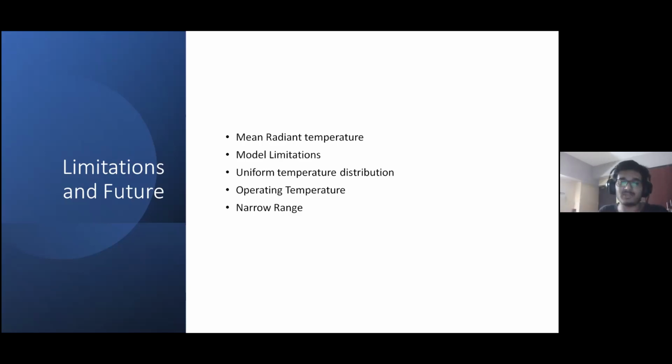Now, this is because we have assumed the aircraft to be an absolutely adiabatic closed system in which there's no heat exchange with the outside. This is pretty obviously not true, because especially when you're flying in daytime, there can of course be radiation coming in from the window. You can also have radiation falling onto the aircraft and the aircraft's external body heating up, and that heat actually being conducted into the aircraft's inner skin and then being conducted inside.